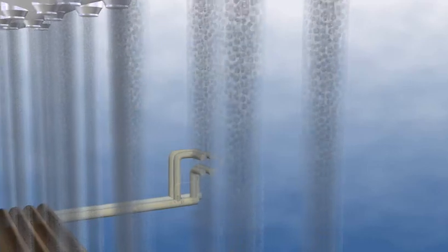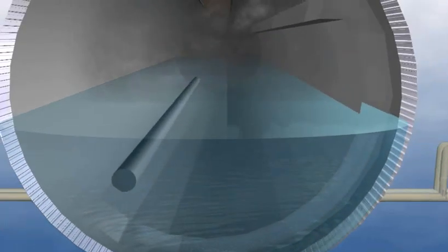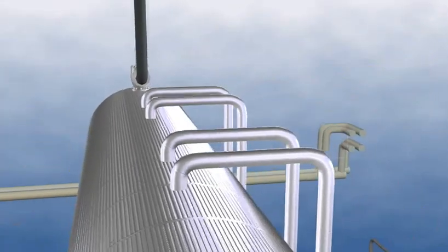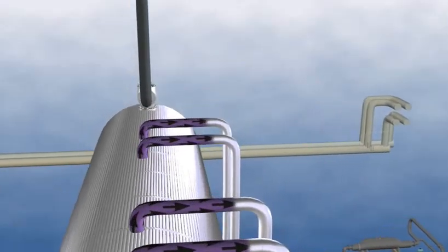The steam-water mixture coming from the evaporator enters the drum in the primary steam separator, where water and steam are separated. Before leaving the drum, the steam passes through the secondary separator, a wire mesh-type steam dryer, and leaves the drum through the saturated steam line.